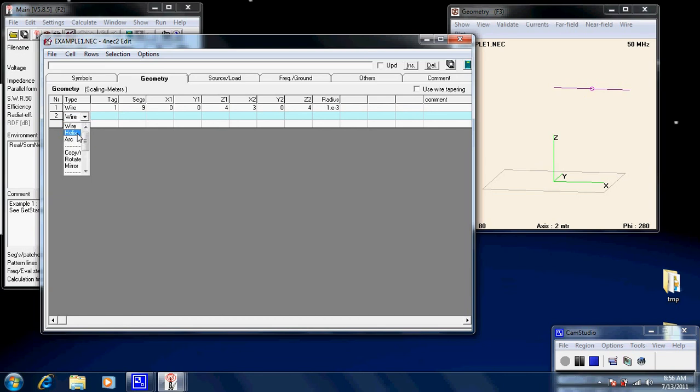Now, you can go through here and just add another one. Let's say we can put in a helix, an arc, or whatever you'd like, but let's just put a wire in. Again, we have tag 2. Let's make it 9 segments. Let's make this 1, 1, and 3. And let's make this 4, 5, 5, and 5. And here we'll make this 1e minus 3, which is just scientific notation for those people who obviously know it.